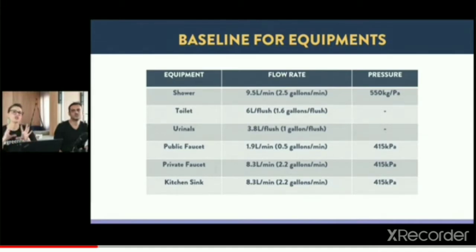If you look in general, when you are speccing your water fixtures, sometimes there are brands, and I've seen it nowadays, brands that are still telling you that you won't get a good shower if you don't have anywhere between 15 to 20 liters per minute on your shower. And this is so unsustainable and so wrong, because you do have the possibility of having a quality shower with a lower amount of water per liters per minute.